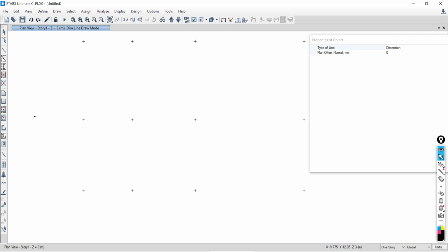If I click somewhere else, like suppose I click here, again the measurement starts. Your software is going to measure the distance between the two points. So if you right click on your mouse, the continuity will be off. Your command will be partly stopped, but it is in active mode. Then what you need to do is go to the Select Object option. Once you click over that, the command will be off. See, the dialog box is removed. Is that all okay?